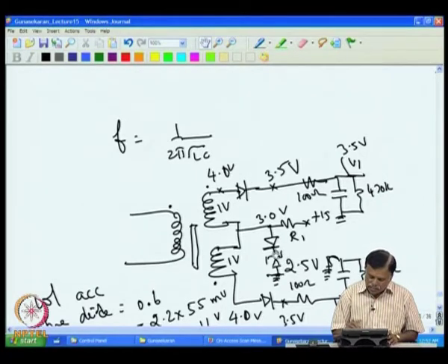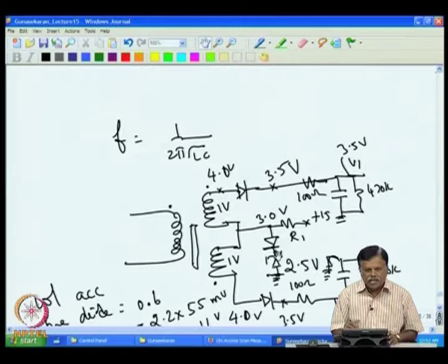Now, this zener is mainly added to push the voltage to one side, because by adding this 2.5 this already gone to 4 and you will not get minus voltage, and that is good because most of these diodes have a low voltage capacity. So, that is also good, plus we also need this zener for another purpose. Even without this zener it can be done, by directly grounding one can remove the voltage, but floating one side positive gives a better result.